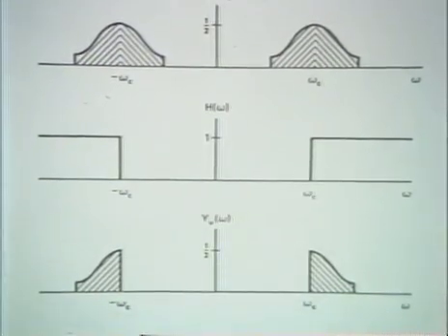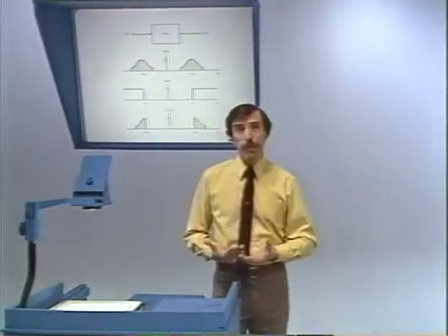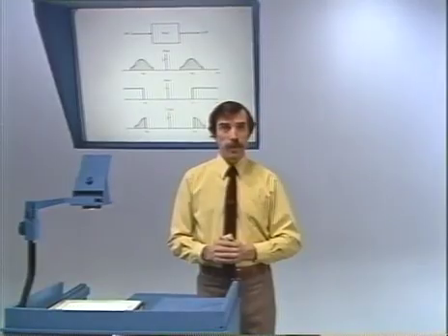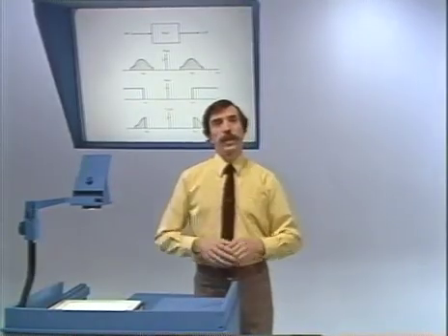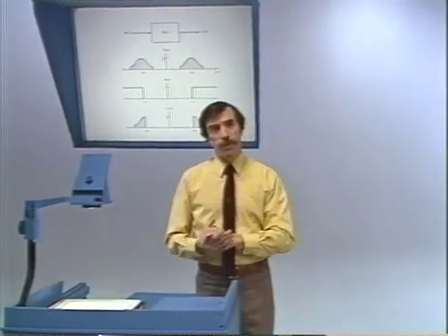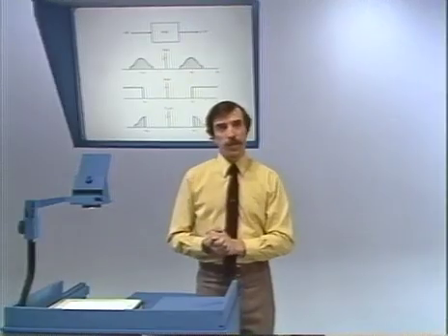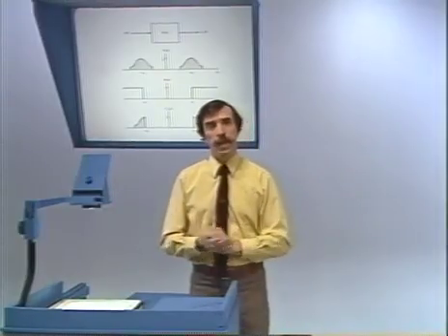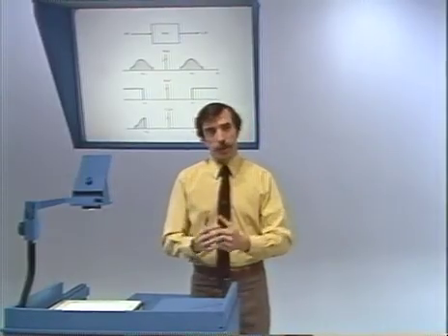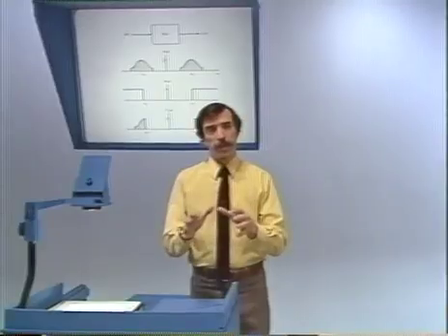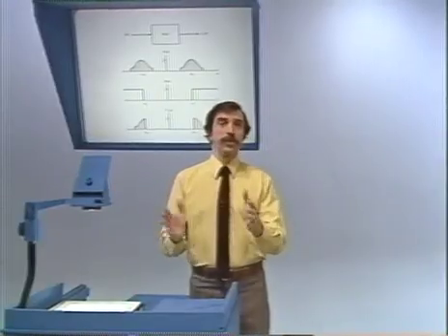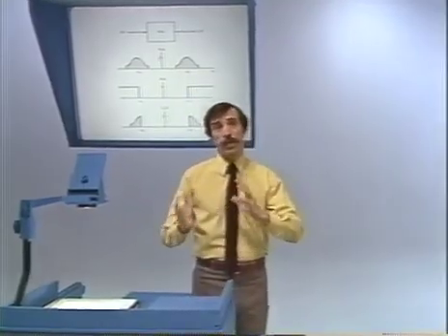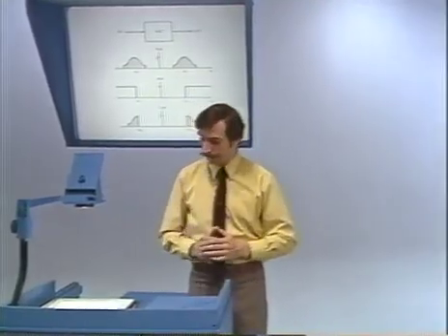And this, in fact, is really the basic idea behind single sideband transmission. Again, there's a trade-off. It's clearly more efficient than double sideband transmission, but it also has the complication or additional issue that the modulator becomes a little more complicated because you need this filtering operation or some equivalent operation to get rid of the unwanted sideband.